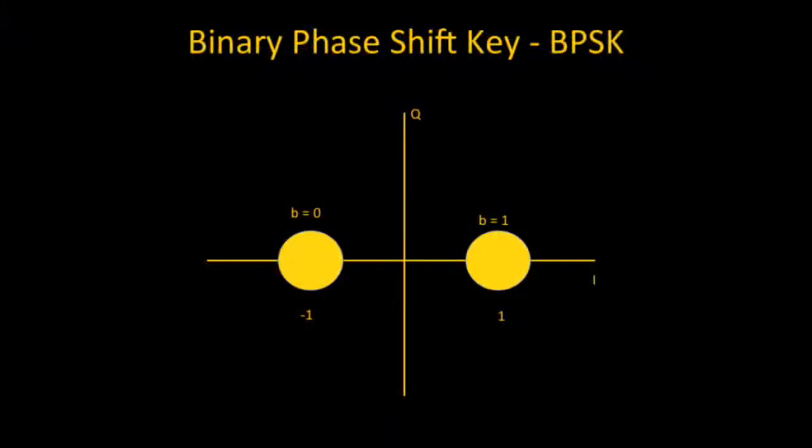Okay. So for the QAM modulation that we talked about, this is a really simplistic picture. So the very low data rates, you'll see some BPSK. This is referred to as a constellation chart. So if I was to give each and every one of you a bow and an arrow, and you were to draw back the string and try to shoot an arrow at these dots, basically if you aim left or aim right, you have a pretty good chance of hitting the target that you're trying to hit, okay? So this is in a very low signal noise environment. There's a high margin of error. You can still get some pretty accurate transmissions. The downside is you're not sending a lot of information. There's not a lot of bits going across with each symbol. It's a one-to-one relationship here. Each symbol is 1 bit.